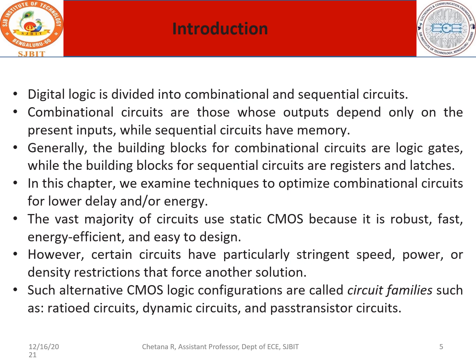So what exactly are circuit families? The basic concept of CMOS is retained with modified changes. The CMOS concept is retained, and in addition we have a few more changes in the circuit, and we call them ratioed circuits, dynamic circuits or pass transistor circuits. Like this we have many more: pseudo NMOS logic, clocked logic, so many things, but here we focus our concentration on ratioed logic, dynamic circuits and pass transistor circuits.